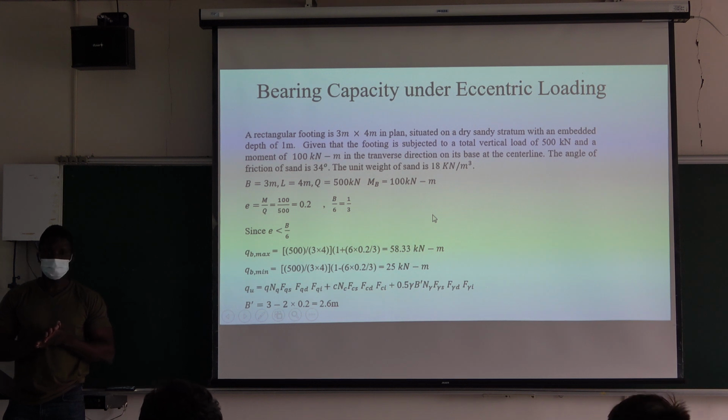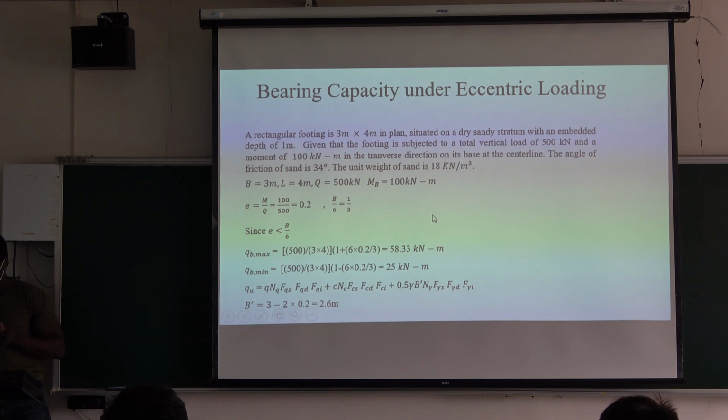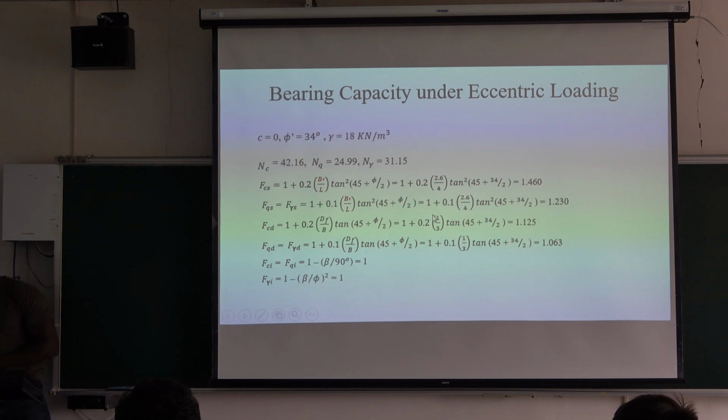Anything else? Yeah, so for this part, actually, the procedure and everything is pretty similar. If you understand what you did previously, that's the typical math of bearing capacity problems, then you just need to put in mind a few basic things. Just make sure when you're calculating, you substitute the B prime where you need to. That is specifically for this part.